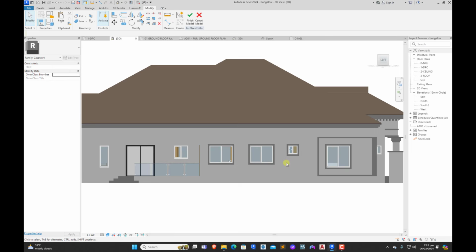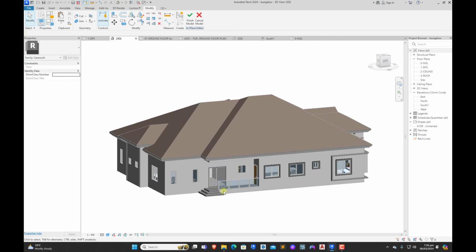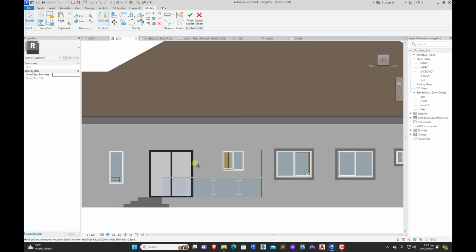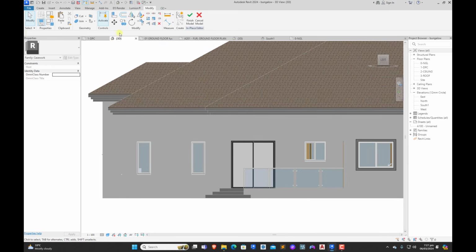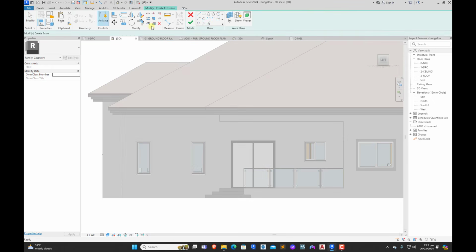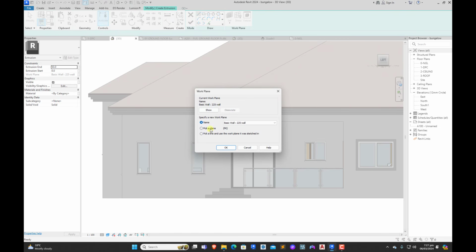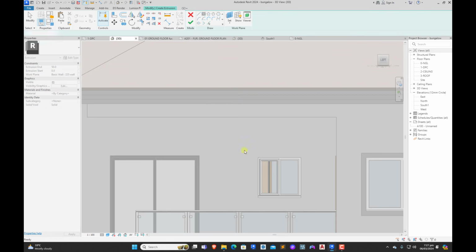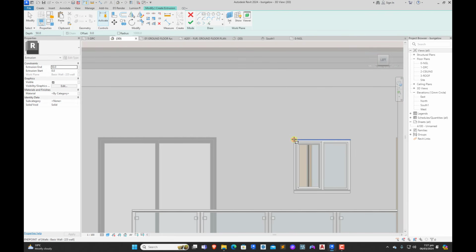Click on good. Now you've seen your extrusions everywhere. The next thing you're going to do is to pick a plane and put your window hood on this side part of the building. Okay, now for us to do that, we need to come back to extrusion, set, pick a plane, okay. Then we draw our window hood, just the same process.